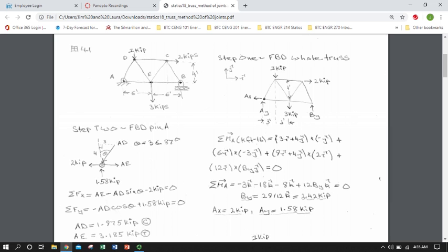In this case I actually wrote out the full cross product. I could have used geometry and just found the actual offset r distance from each of these forces being directed vertically or horizontally, but I did have the triangle directions, so I used the cross product in this example.